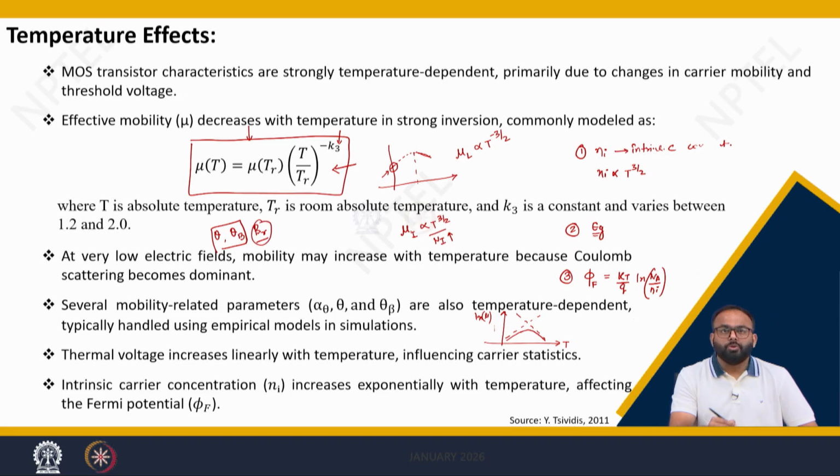This is related to the extrinsic source resistance equation. These all are dependent on temperature. But in general, when you model these equations, these are considered fitting parameters because it is really hard to calculate the impact of temperature on them. So, in simulation tools also, you will find that these are fitting parameters you need to tune to get a best fit in comparison to the experimental data.